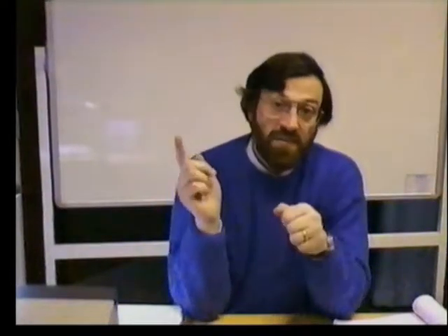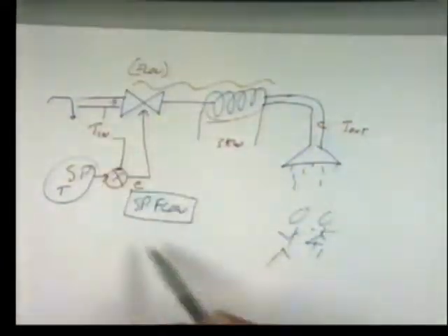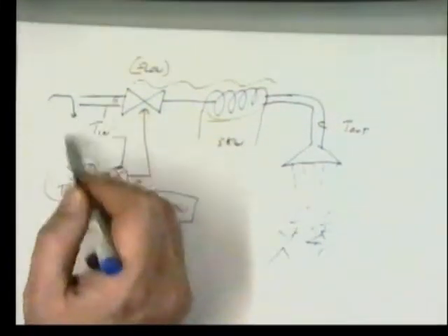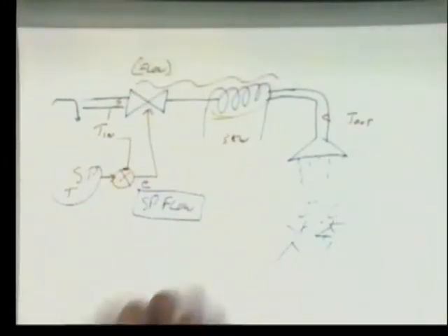We have feed-forward predictive control. I'm not going to go into the maths of it because, of course, the mathematical model is different for every system. Your job as the programmer is to develop the mathematical algorithm that represents the whole of this control system, and then implement that in code, feed in the inputs from which you derive the output flow rate. So there we have feed-forward predictive control.